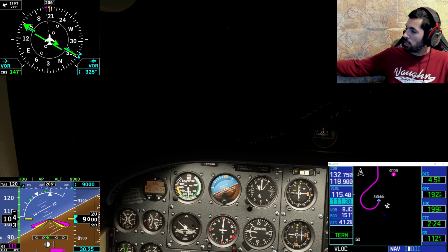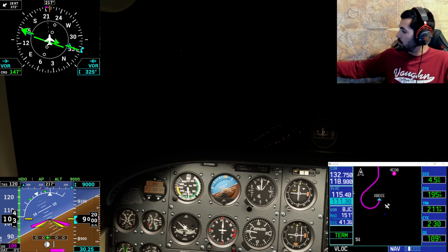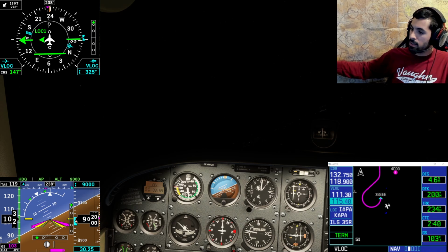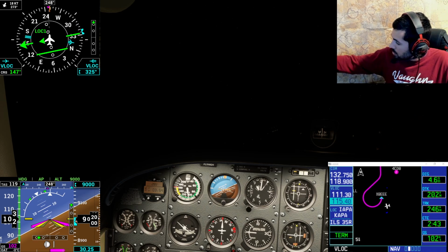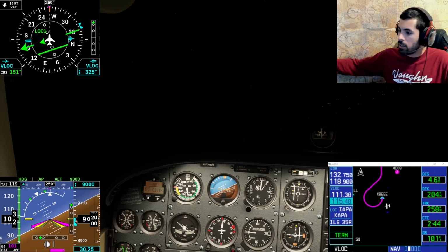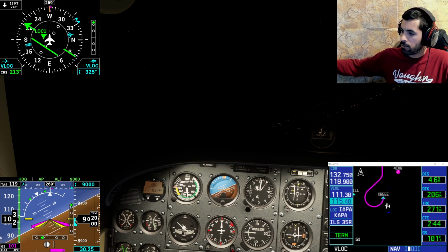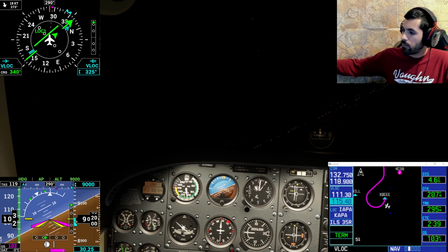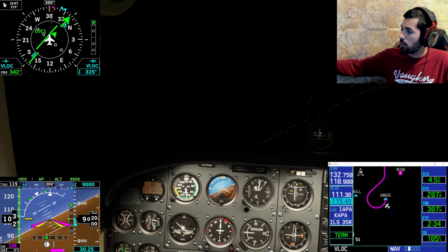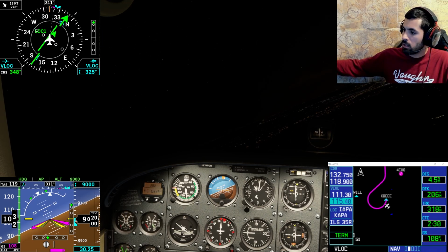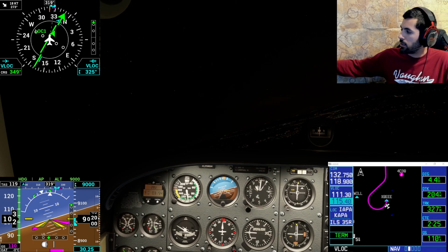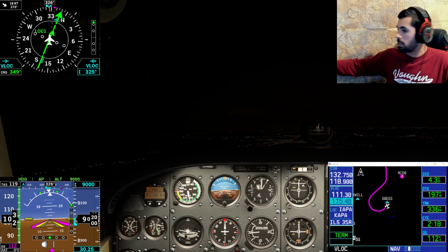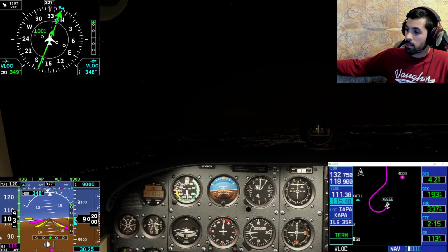But then once we do that, we're gonna switch over to the ILS, capture it, and the course for that really should be on 350. Now, typically, it doesn't care. There's a distinction between my HSI and the VOR inside the aircraft. It's going to line up no matter what because it's a fixed radial.